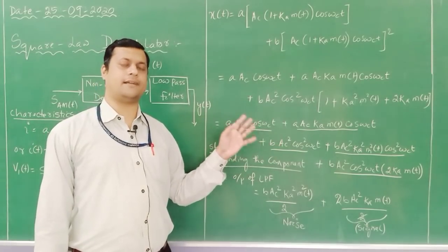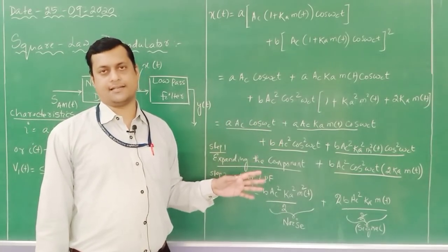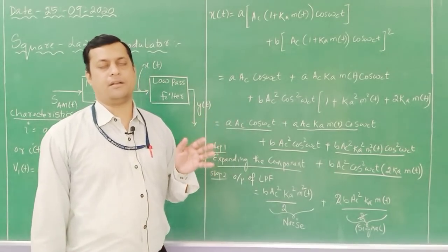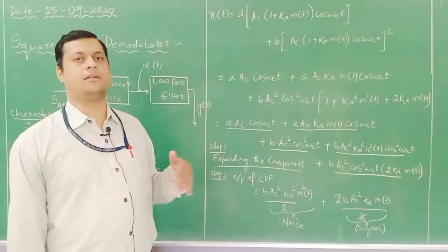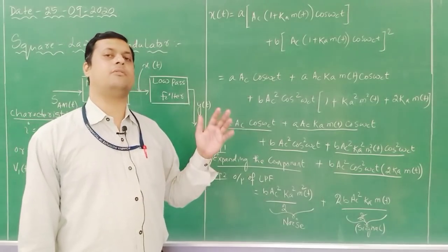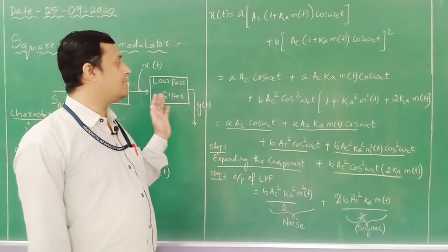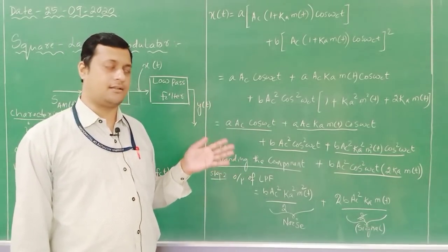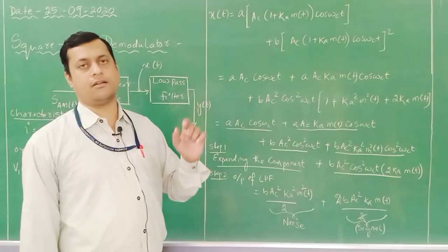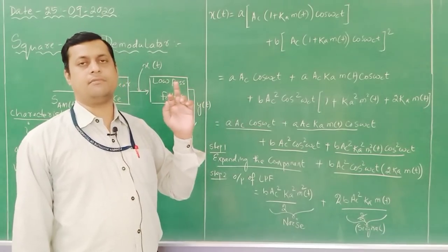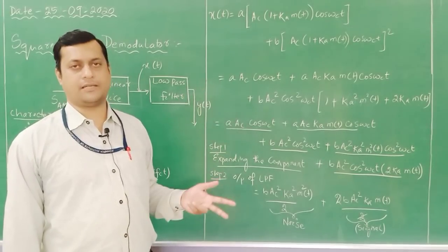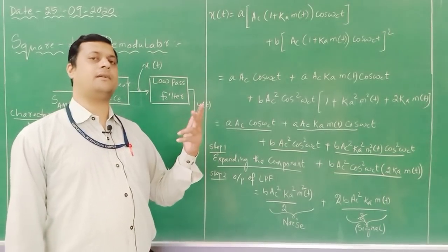At last we need to extract the modulating signal, which will be the output of the LPF, and the output of the LPF will decide whether we have recovered the original signal or we need to tune it. These are the basic steps we discussed in the last class. First, the signal enters a nonlinear device. The received AM signal is processed through a nonlinear device, followed by a low pass filter, and then a DC blocker.